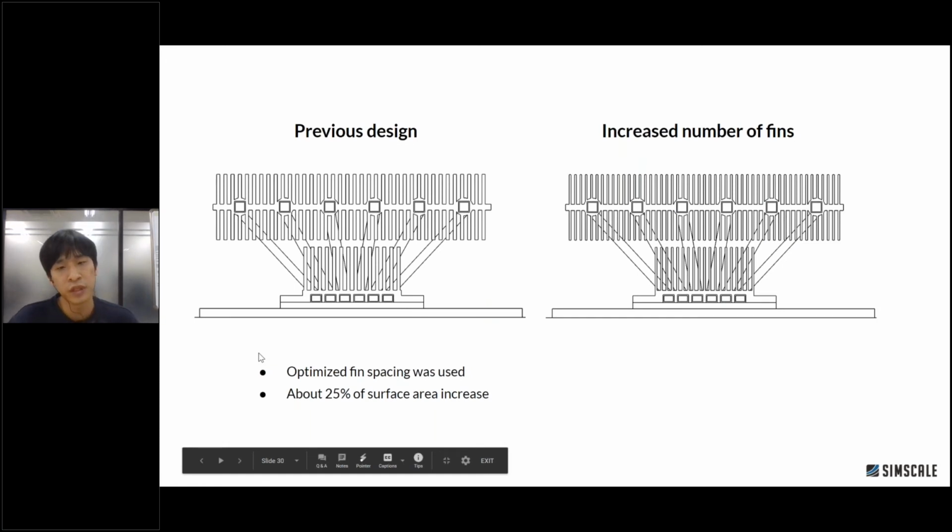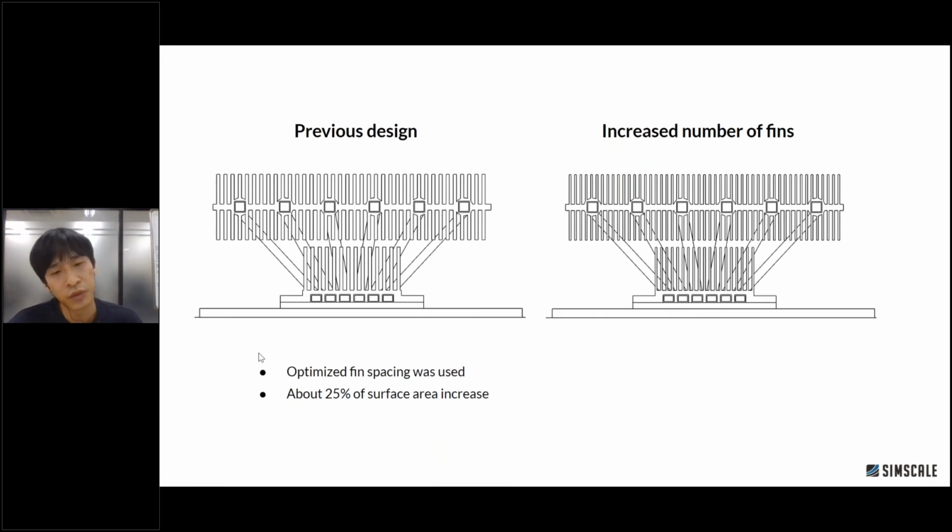And as we already had this kind of data when we made the prototype version, the fin spacing was quite close to the optimal condition. And in the new version, we tried to increase the number of fins by using fins of smaller thickness, which is harder for the manufacturing. But if it increases the performance, then it is gonna be worth it.